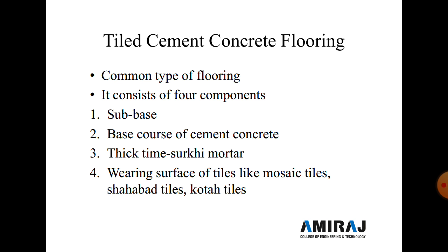So then after filling the gaps or joints, the flooring is cured for 7 days, and after curing for 7 days, grinding or polishing is done by machine. So here in tiles work, no polishing or grinding is required. In Kota stone or marble or granite, grinding or polishing is required after 7 days.